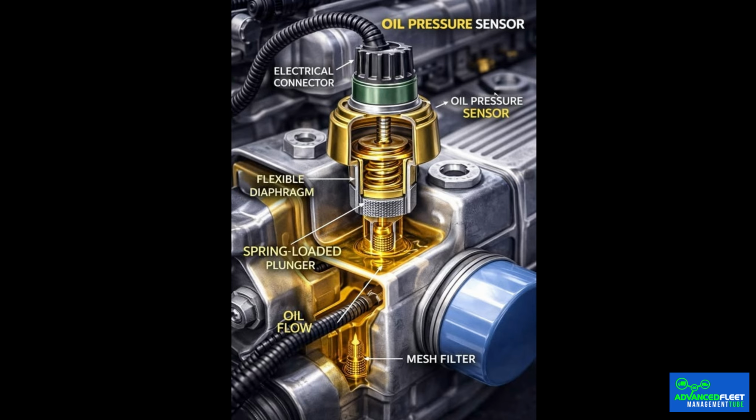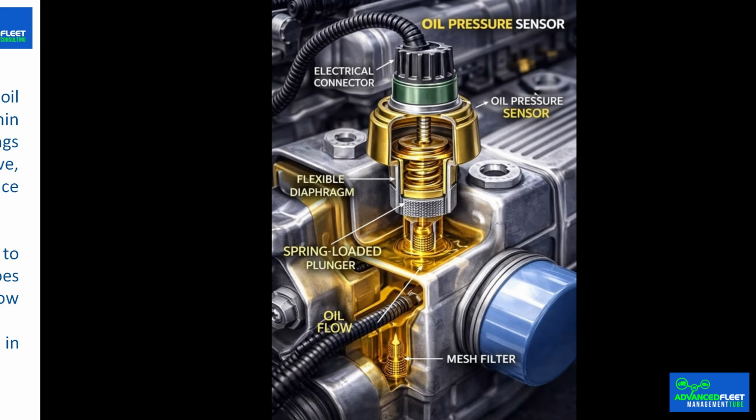Failure of the oil pressure sensor. Modern vehicles are equipped with a pressure sensor that constantly monitors oil flow. Depending on the vehicle, this sensor may be located in a section of the circuit within the engine block or at the outlet of the oil filter. This sensor may provide inaccurate readings due to potential internal damage that may have developed over time. If the part is defective, it is usually replaced, as repairs are not typically performed. The typical cost of this service ranges from 30 to 200 euros, depending on the type of vehicle.